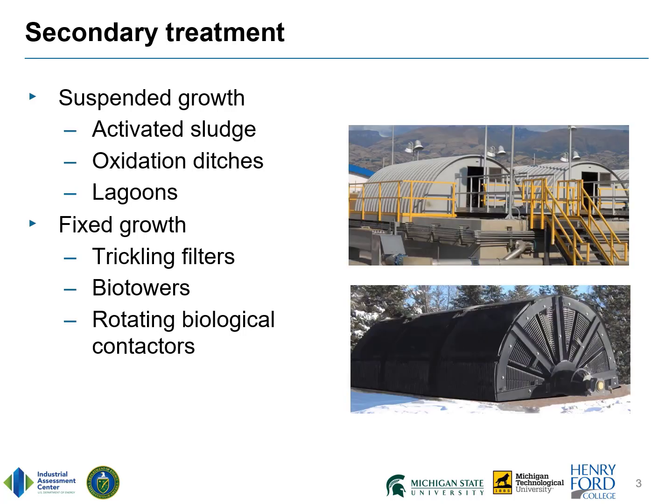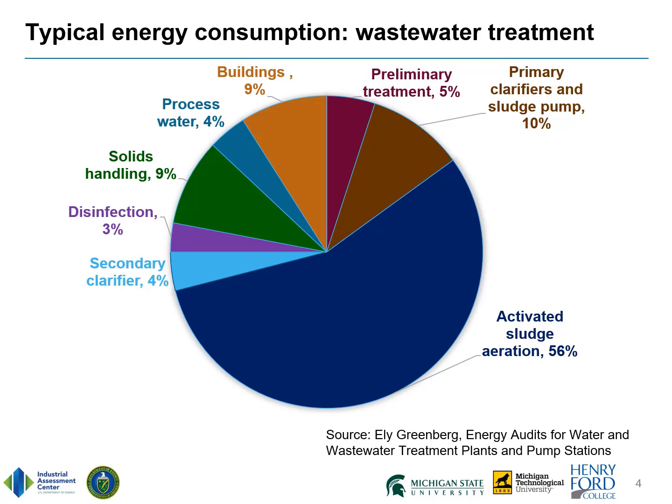Lastly, rotating biological contactors are similar to trickling filters in that the microorganisms are attached to a solid surface, in this case, rotating corrugated discs. The wastewater is aerated when it is in contact with the atmosphere. Roughly 90% of the energy consumed at a treatment plant is from the wastewater treatment process, with aeration being the single largest energy consumer. Blowers, like pumps, are large users of energy.